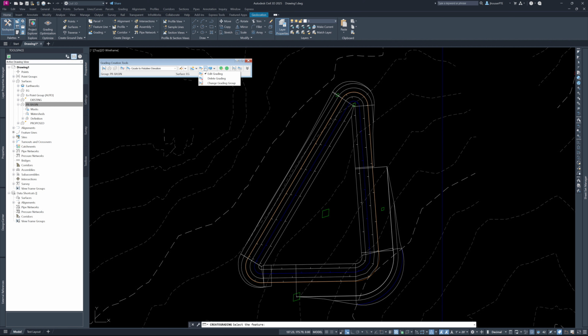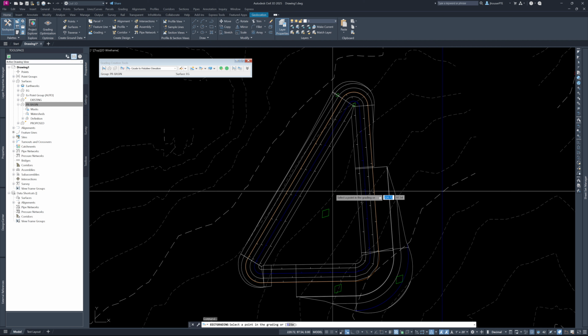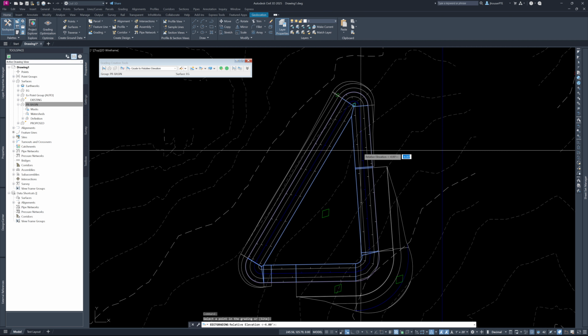Like I said earlier, if the inside grading of your basin has to be 4:1 instead of 3:1, you can do that. You can just click on that. Now in this case, you'd have to go in the area in between your original feature line and the bottom, but not here because this is your infill. It won't let you change that. Now, okay, we want to change this to be, oh, this is relative elevation. Let's say we need another foot. We could always hit -5, slope, and that would do it. That added another foot to our inside depth.